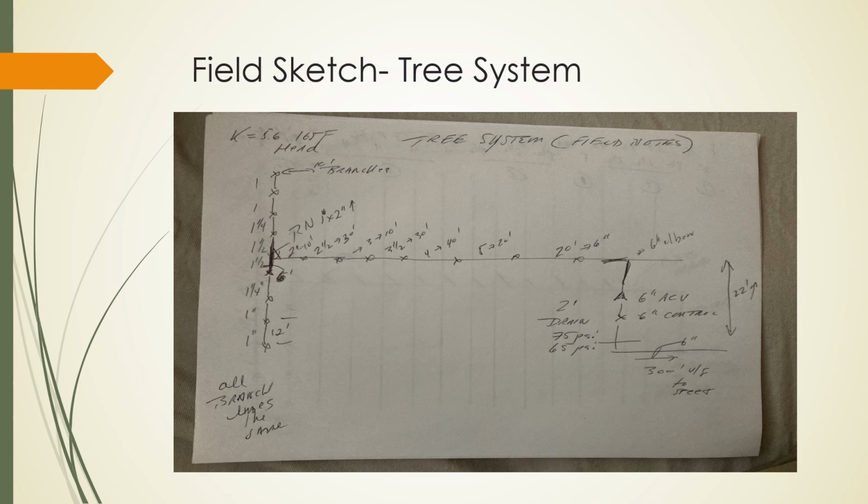So right now, I pretty much make a determination as to what's going on with this system. It's an ordinary hazard system, probably, who knows, designed in the 60s. It's got a 75/65 2-inch strain test, pretty good. A 6-inch line is not a very big line, running 300 feet. This is going to put out an ordinary hazard density, 0.2, 0.25, somewhere in that vicinity.